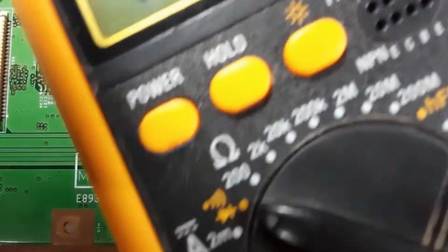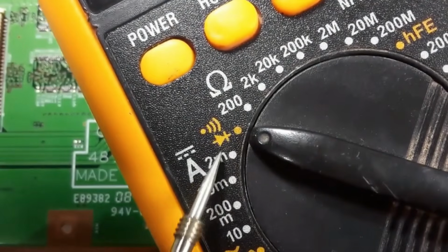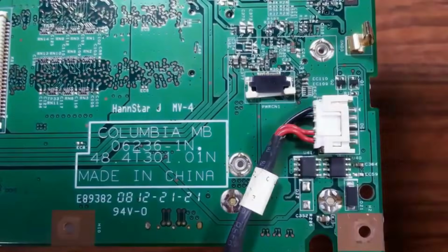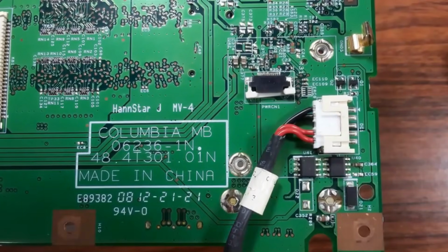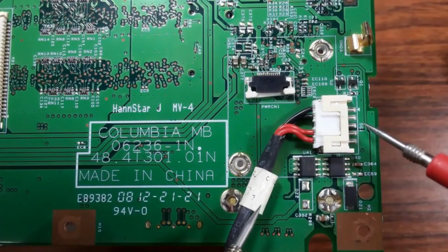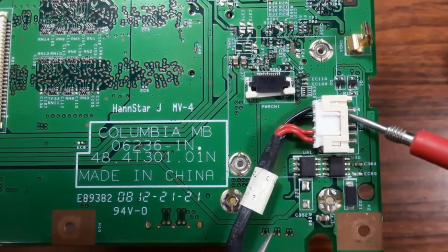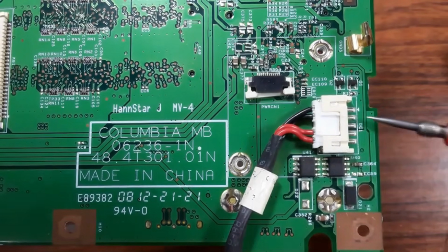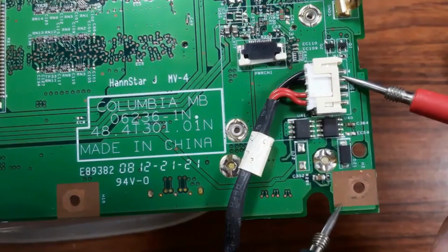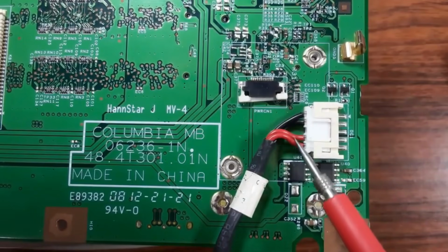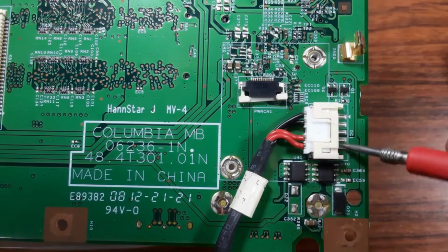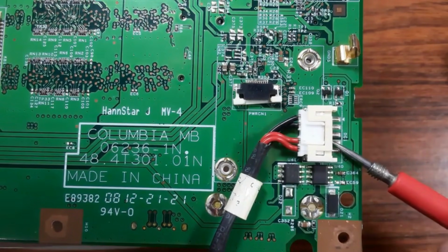So always put the multimeter to the buzzer option and check the continuity. The continuity is good, and check whether these two are connected to the ground. They should be connected to the ground. Why? Because we have here the black wire. So let's check it. Also the signal is connected to the ground. But for the red wires, of course, this is a positive wire, or the high wires.